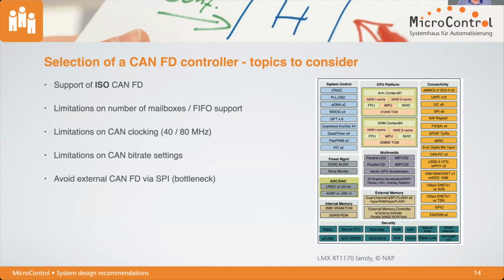And if you really read the very small letters of the data sheet, you see that if you want to enable CAN-FD and run 64 bytes in a CAN-FD message, then you don't have any FIFO support anymore, and the number of mailboxes is limited from 128 to only 7. Surprise, surprise, especially when you already have running software, for example for classical CANopen, and you just want to port your software to CANopen FD, then you will find out that it doesn't work with that hardware.